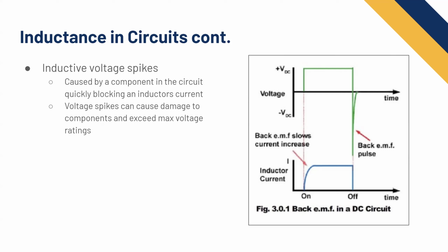So you could have a pulse like this, where on the bottom you see the inductor current starts charging up, and then if we suddenly cut off that current with a switch or something, the voltage is just going to go as low as it wants. The inductor will decide what it wants and it'll do it. So it's really up to us to make the inductor happy. You're not going to stop the inductor from doing this, but you can clamp it and send the energy elsewhere.